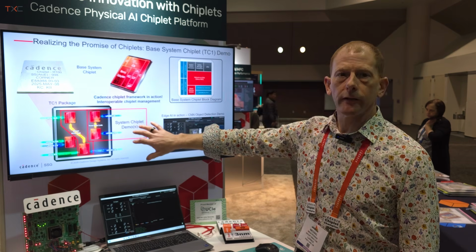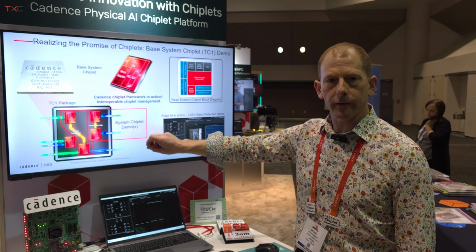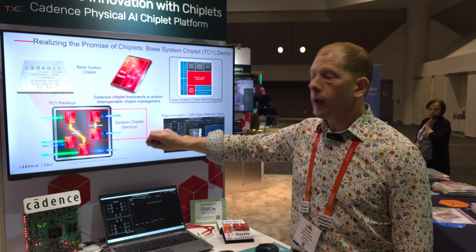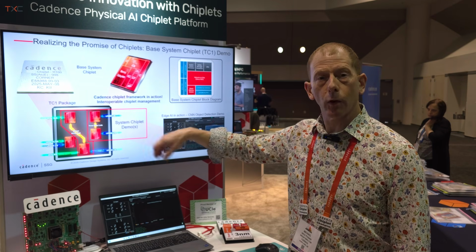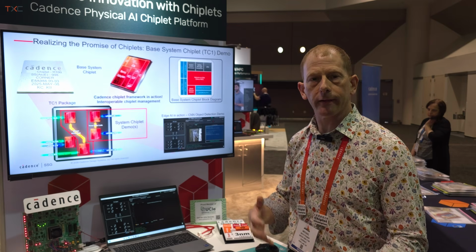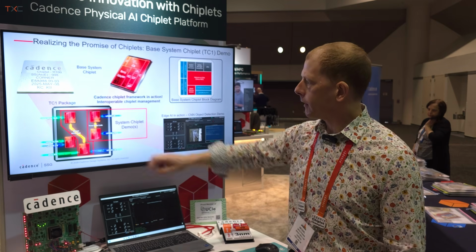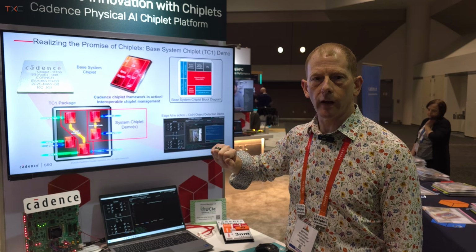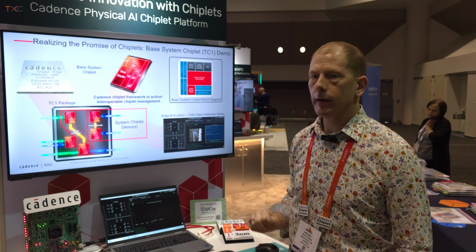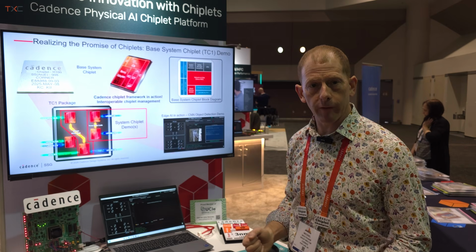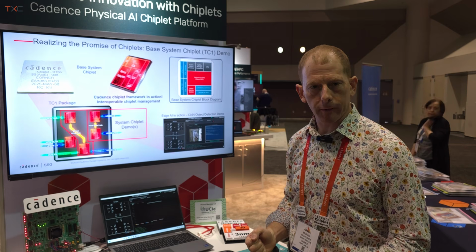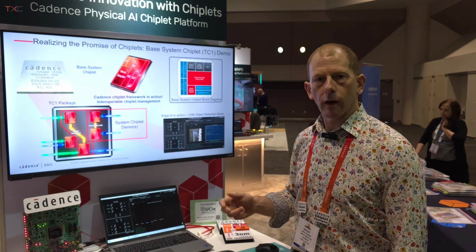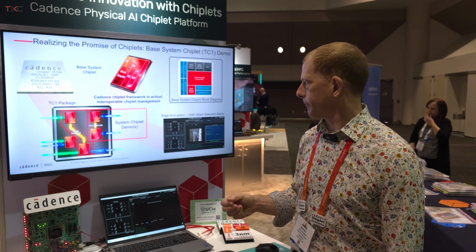The silicon has 5 die packaged inside of it. These are all identical die, configured in different fashions so we can test between primary and secondary chiplet operations. 2 die are linked via a 7mm UCIe link, and 2 die are linked by a 25mm organic substrate link. These execute at 32 gigabit across UCIe standard.